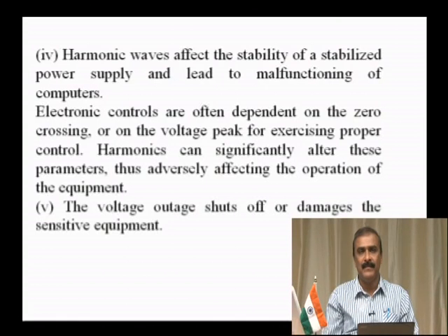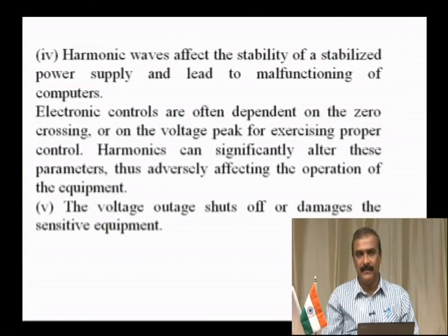Harmonic waves affect the stability of stabilized power supply and cause malfunctioning. It is quite common. How do harmonics affect? See, you have electronic controls that depend on zero crossing or voltage peak for exercising power control. This concept we have discussed while discussing converters and inverters.